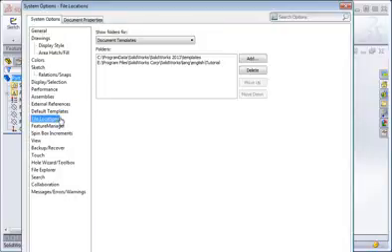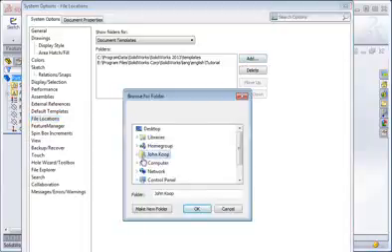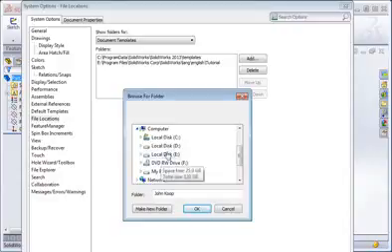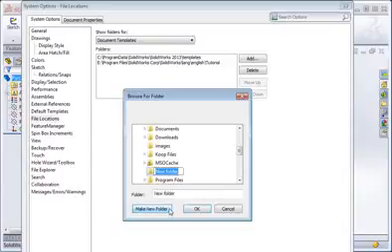Click File Locations, and now you can see where template files are stored. If you recall, there was a Tutorial tab, and as you might have guessed, template files are stored in this folder. We're going to store our first template in a folder named TEDCF. Click the Add button, and then browse to the root of a drive that you typically save your data on. Now click the Make New Folder button, and then rename the folder to TEDCF. With the TEDCF folder highlighted, click the Make New Folder button, and then rename the folder to Custom.